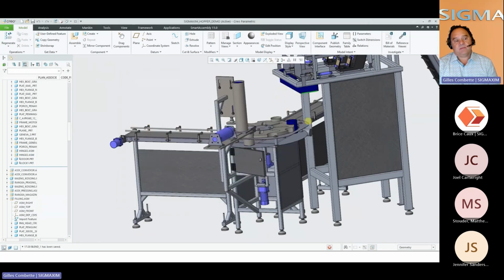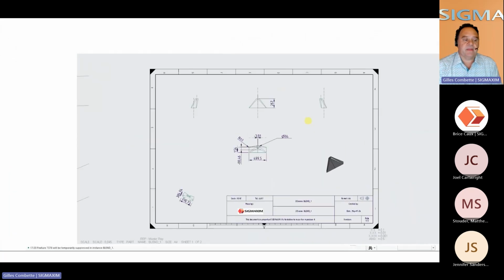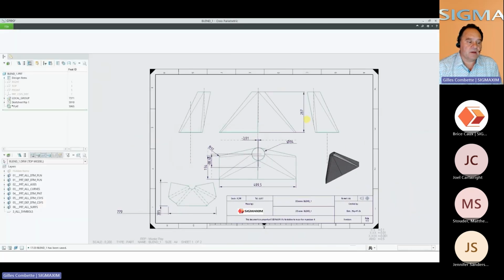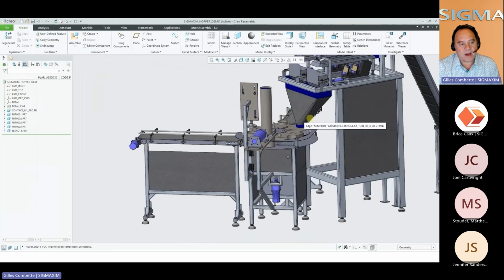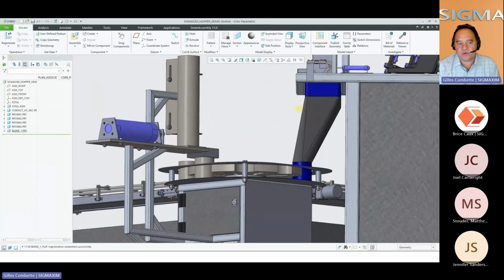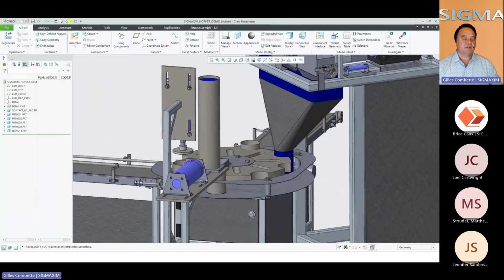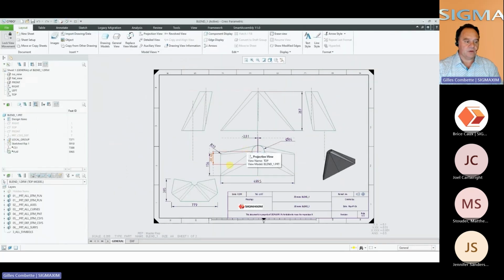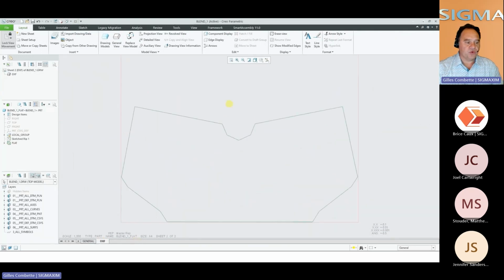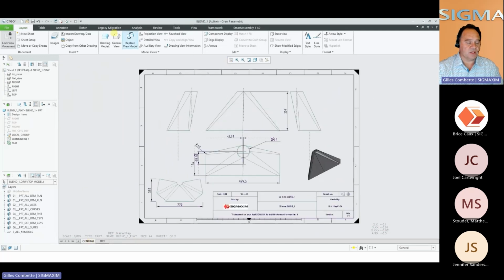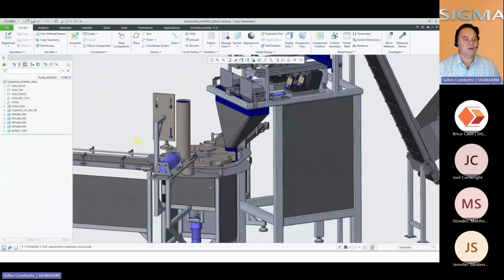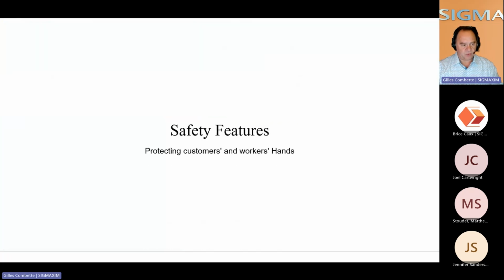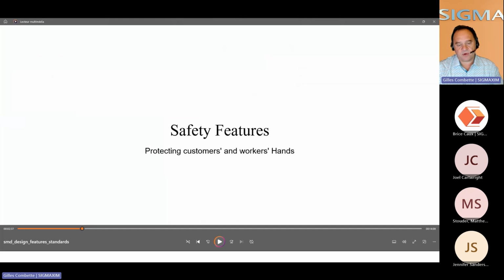And automation for starting models is also very convenient for those models that you are not doing often, that you're doing once in a while, but that are a little bit complicated for you to redo every time. Here is an example of a blended part, which goes from rectangle to round. It generates a full 2D drawing, detailed, with one folio with the full information in 3D and a small flat pattern. And then the flat pattern, scale 1, is ready to export as DXF or IGES or whatsoever for the next player in the process.